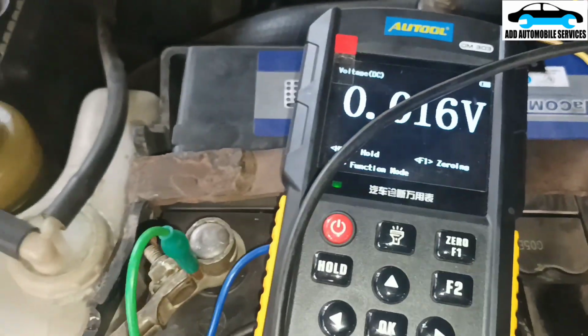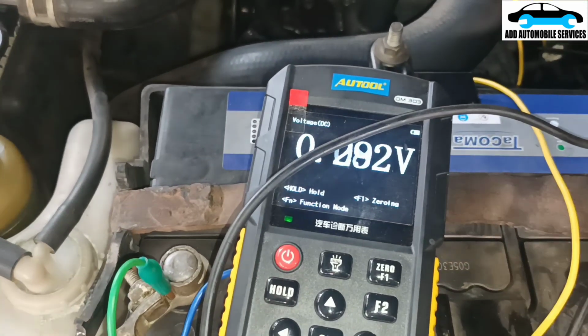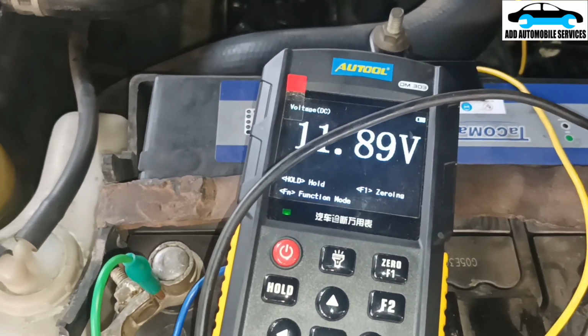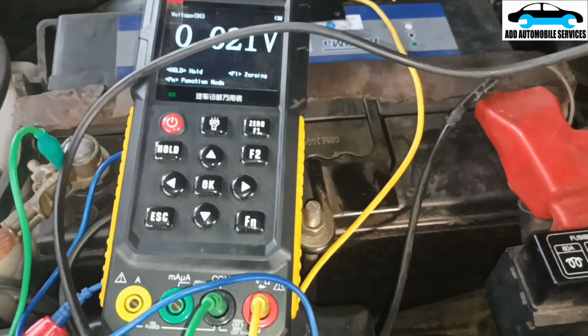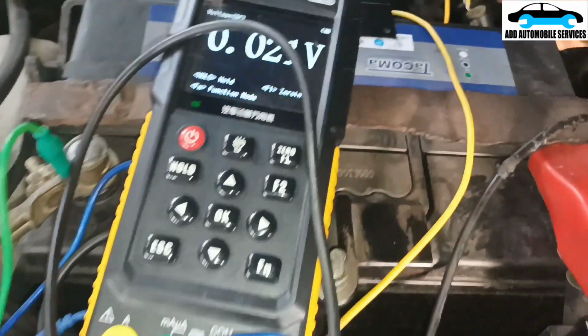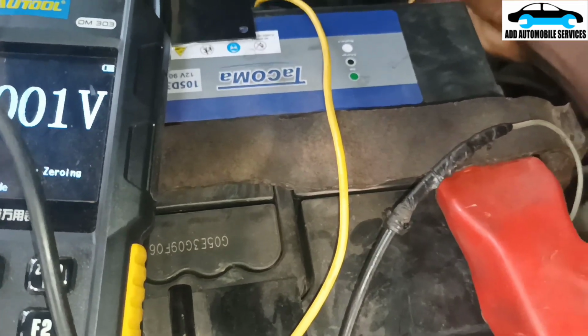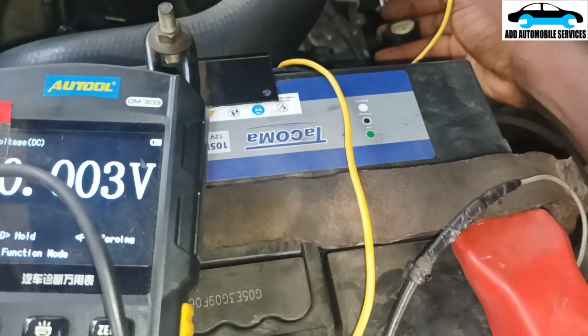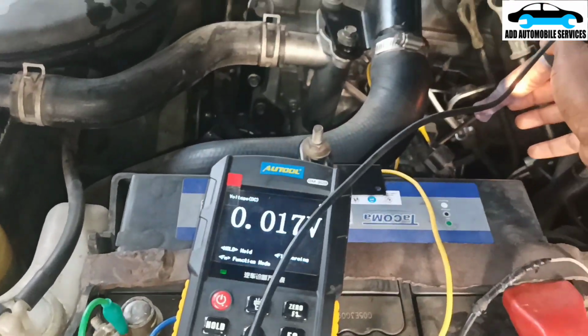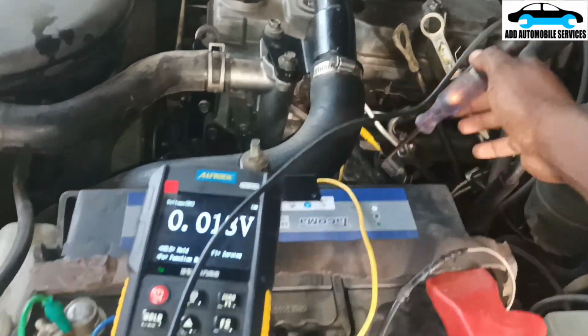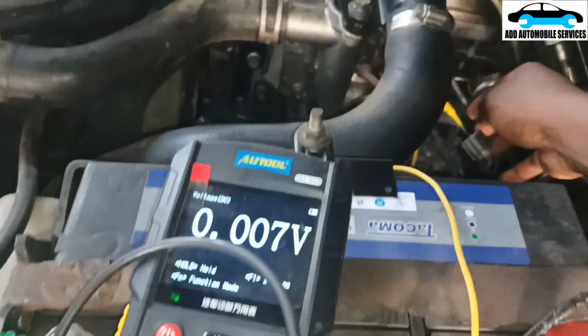So you can see that anytime I touch the test light, it increases the voltage and my test light is not turning on, because that's not the ground, that's the signal line. So let me find, maybe the next one will be the ground, and the moment that's the ground, it will turn on my test light. So let me try and see. Okay, now my test light is on. That tells me that that's the ground. So this is the signal line.